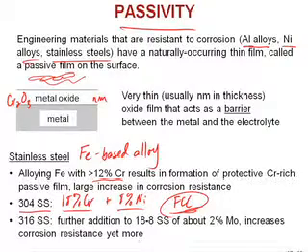And you know that because the knife in my kitchen, we attach it to a magnet on the wall. The FCC phase is not magnetic, okay? But the BCC phase is magnetic, or in fact, we can form martensite and tempered martensite to get that hard edge on a knife. Okay? The handle, if it's a stainless steel handle, will be an FCC material for forming and corrosion resistance.